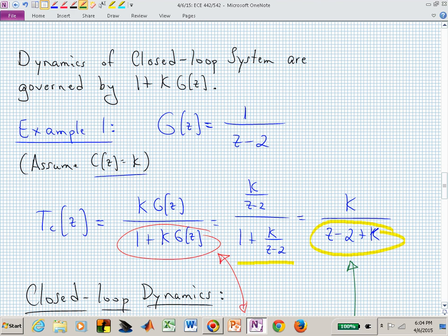So I can try to explain that. That was in an earlier lecture, but if you cancel an unstable pole or an unstable zero with your controller, that's going to produce an internal instability. That's the cleanest way to maybe say that. Meaning you might have now an unbounded error signal between your reference and the error. So you have these different transfer functions in your closed loop system, wherever my block diagram ended up.